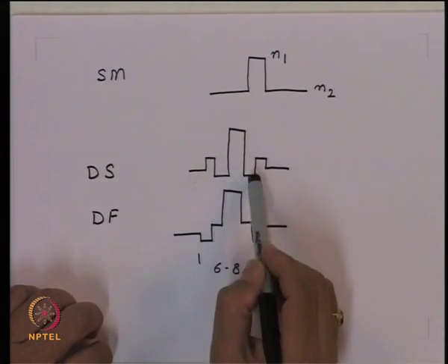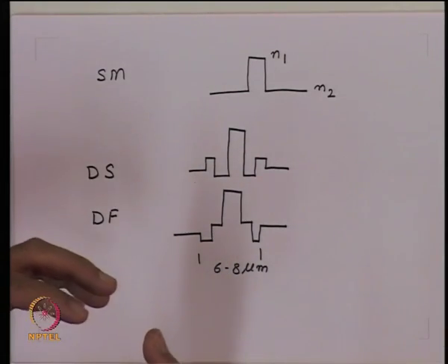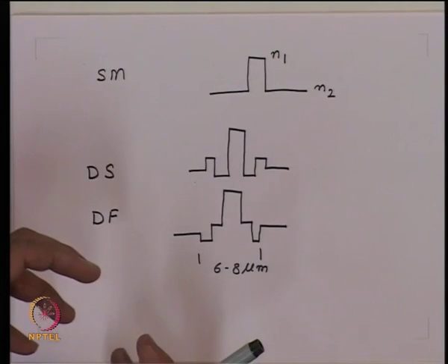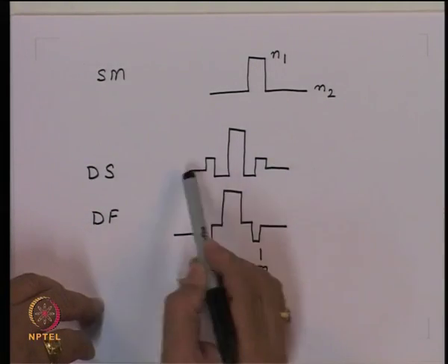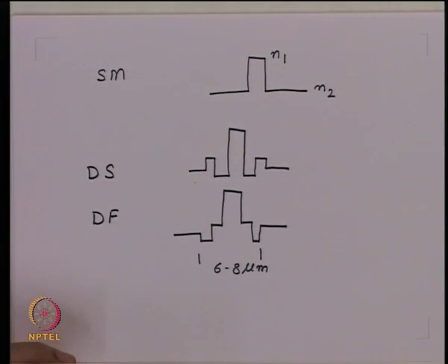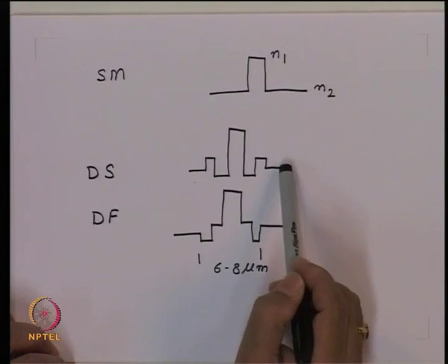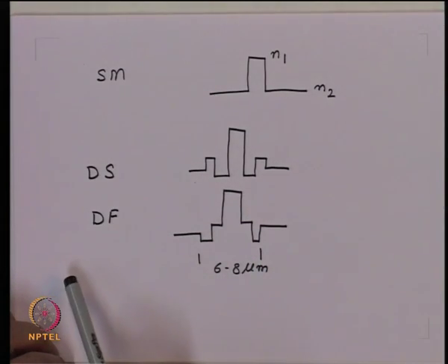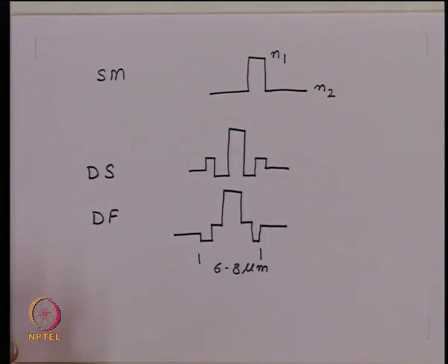So, you have an inner region and then a ring around it, and then another ring around it, so you have a multiply clad region that we call the core, and then where the refractive index becomes constant, that we call the cladding. So, the first thing to note is that there is no one N1, though you may say N2 is the refractive index of the cladding which is constant, but we do not know what N1 is now.